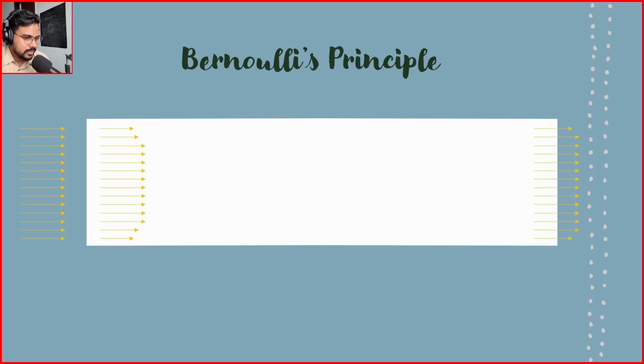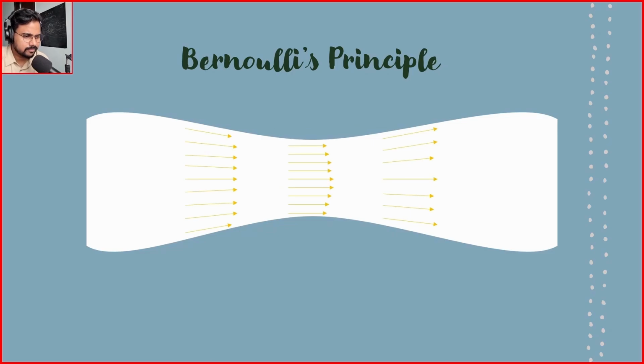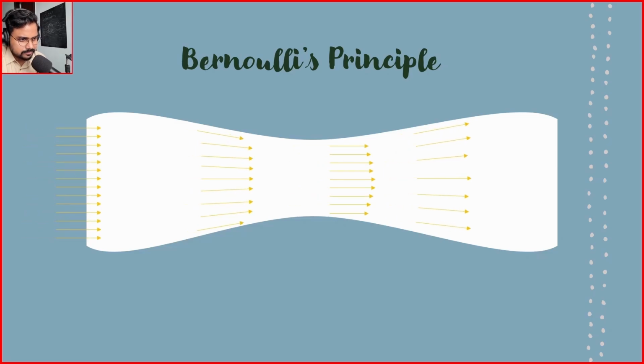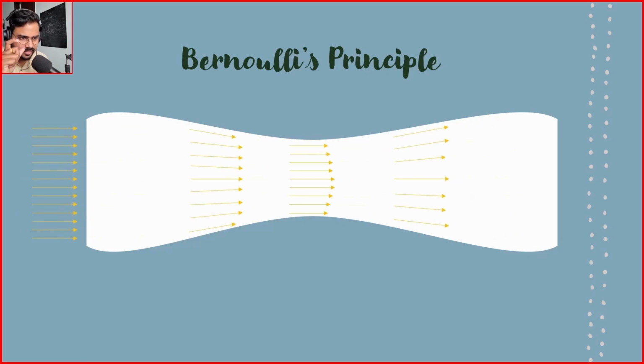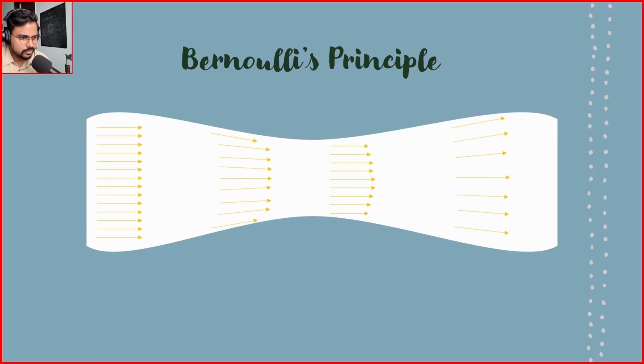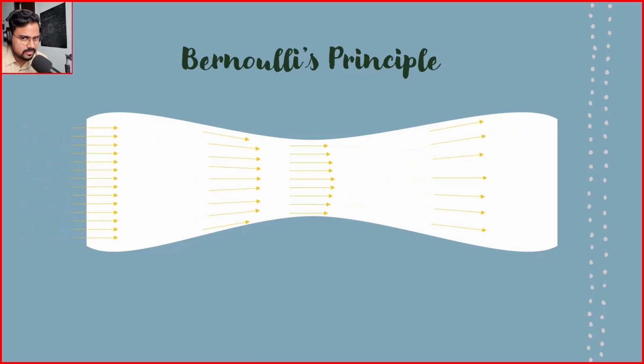We can see that the fluid is following a certain parabolic sort of a profile, because the fluid near to the walls of the pipe tends to stick to those walls and fluid away from those walls tends to have higher velocity. Now, what exactly would happen if I would just pinch the middle a little bit and want to understand what is happening to my flow velocity in that instance? Well, the fluid tends to accelerate in regions where the area has reduced quite quickly, and it tends to reduce its velocity where the area has increased in that sense.